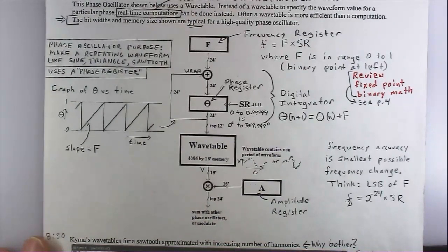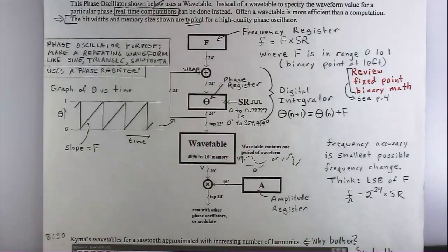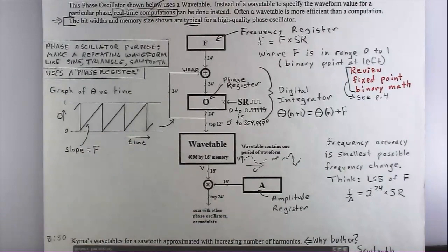And you have to do that. If you don't do that, you're screwed. Okay? So that's what phase wrap means. It doesn't mean, when you get to the maximum, you jump to 0. No, not at all. What it means is you just ignore the carry out and you just keep going. Just let it overflow and ignore the overflow issue, but keep all the lower bits.